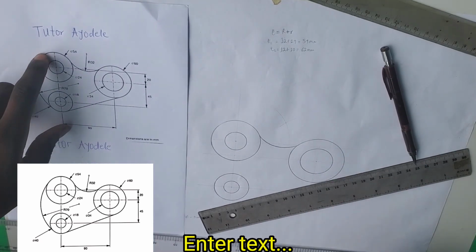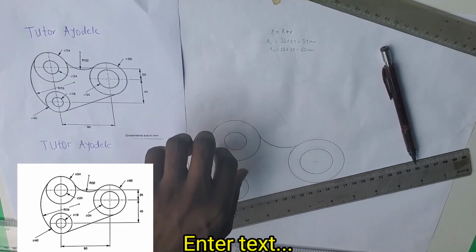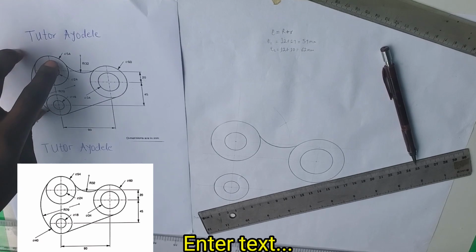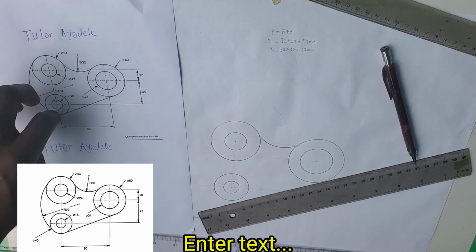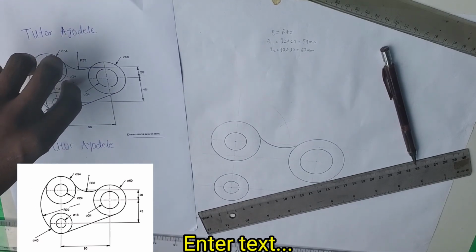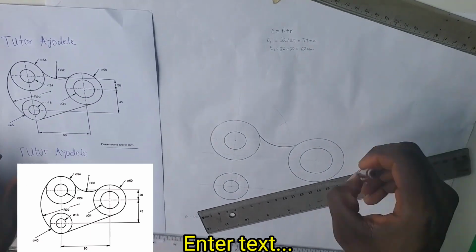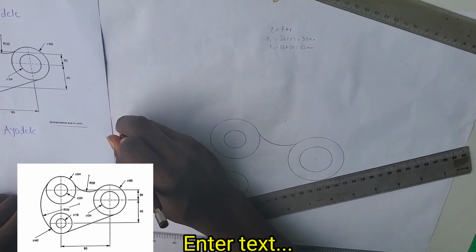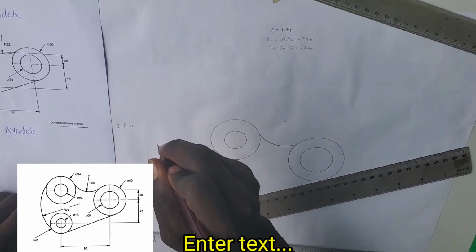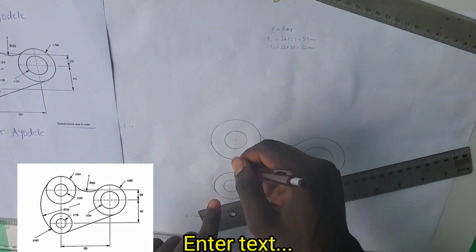Now let's do the internal. This one is internal. Why is it internal? Because it's heading towards the given diagram. If you construct this full circle, it's going to affect this whole thing, because the radius given is 70. It's going to be big and enter into the diagram. That's why it's internal. So to calculate internal, you have large R minus small r. That is the given radius, which is 70, minus the radius of the circles.